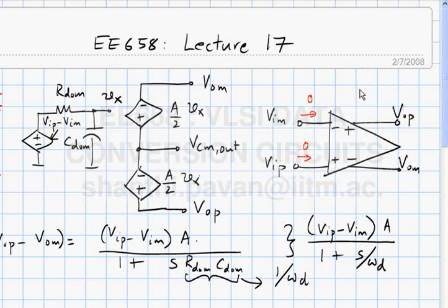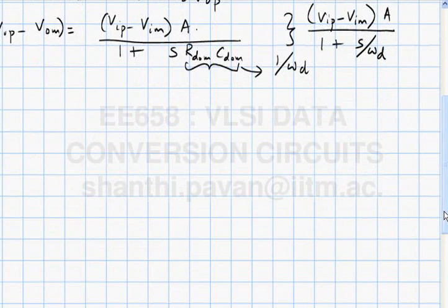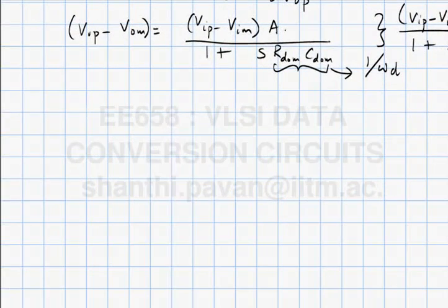Okay. So, let's quickly look at a practical example of a fully differential design. We know that a single-ended design, for example, of a switch capacitor sample and hold is, this is Vi, this is phi 1, this is phi 1a, this is the sampling capacitor. Once we've held the input sampled on the sampling capacitor, it's not just enough if you hold it on the capacitor. You eventually want to quantize the voltage that is held on the capacitor. Whatever I use to quantize shouldn't load the capacitance and steal away all the charge on the capacitor. Then I will be quantizing something which is.